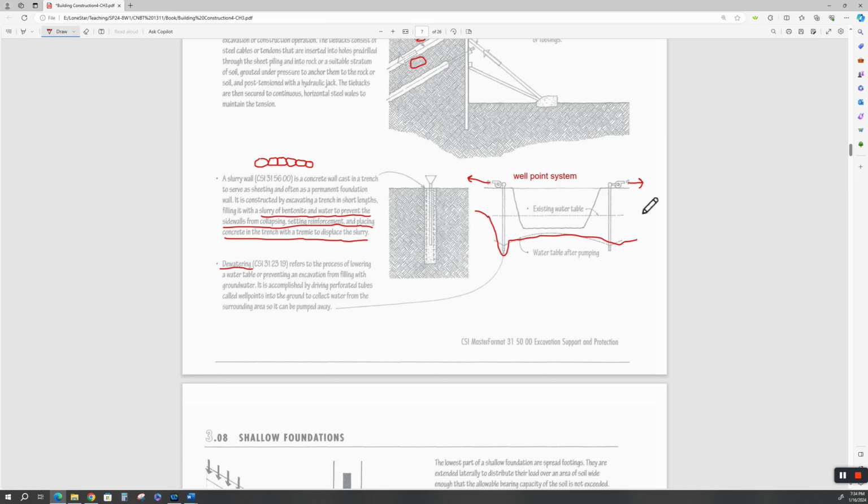length of your construction. The idea is if you're going to put in, let's say, a deep foundation wall, once this water table gets drawn down, you got to get your soils engineers back in here and start doing another soils analysis to make sure the soil is dried out enough that you can start working.